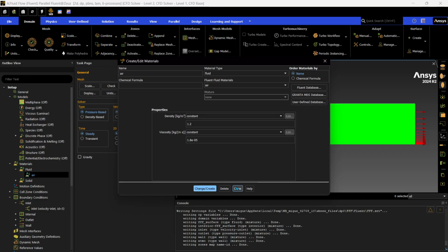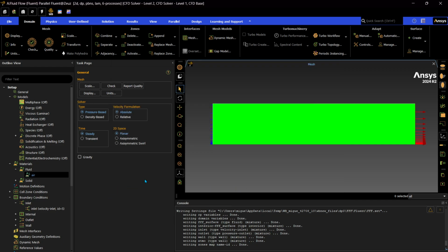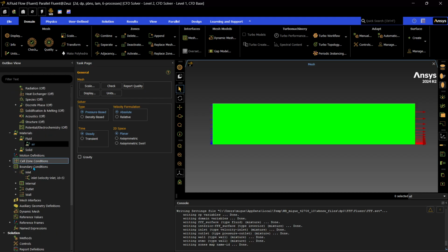There you go. So with these parameters, your Reynolds number will be way less than the critical Reynolds number needed for turbulent flow. So we could make the assumption that the flow here is laminar. And also because the assignment stated that you have to use laminar, but yeah.